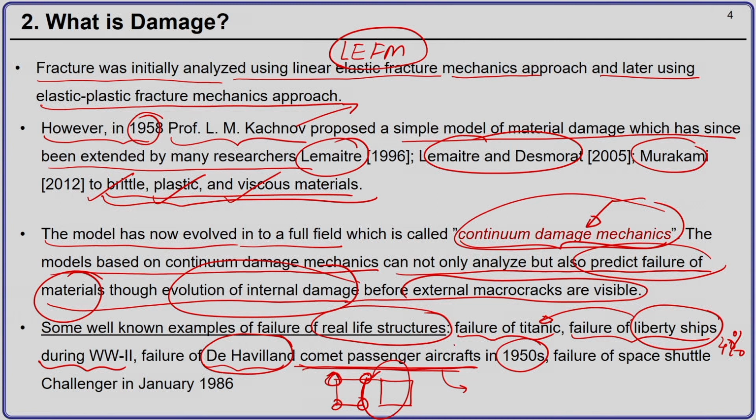Okay. So, when this was found out, Boeing started making windows which were of this shape. So, there was no sharp corner, there was a blunt corner, which led to stress relaxation, and stress would not concentrate, leading to much better performance of the aircraft.